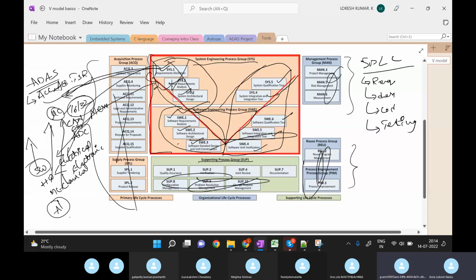If you are keeping your ECU in the vehicle, even if it is minus 40 to 150 degrees, the ECU should not get corrupted. There should not be any corrosion effects in the future, even if water is pouring on the ECU, or even if salt is present, it should not be affected. So by considering all those environmental conditions, they will come up with the mechanical requirements.